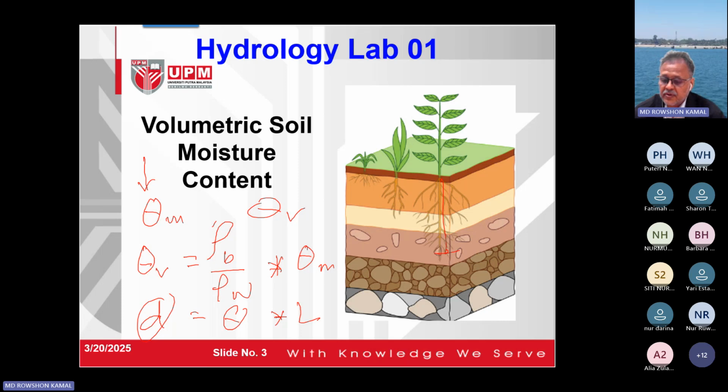When you know the depth of water, it is one of the hydrologic components, because we need to know how much water is in the soil. Then we know the amount of water stored in the soil, so we can calculate the hydrologic cycle. In a hydrologic cycle, you have seen the rain falls on the surface, then it enters the soil, this is called infiltration, then it moves horizontal and vertical, this is called groundwater, and then goes deeper.